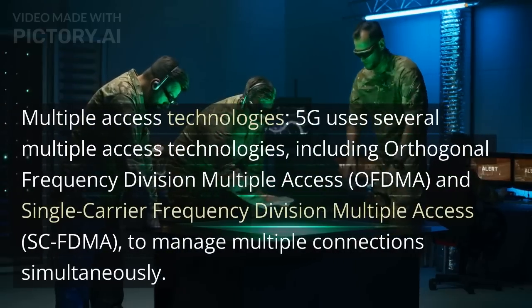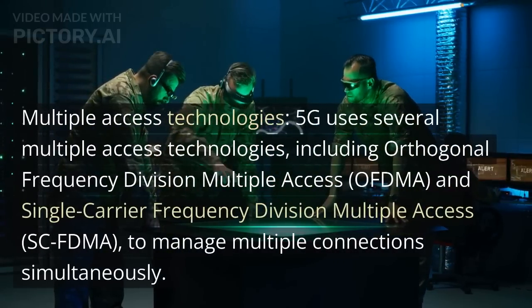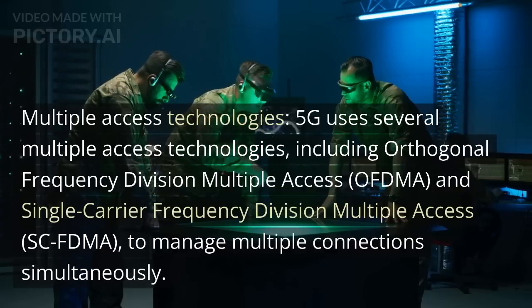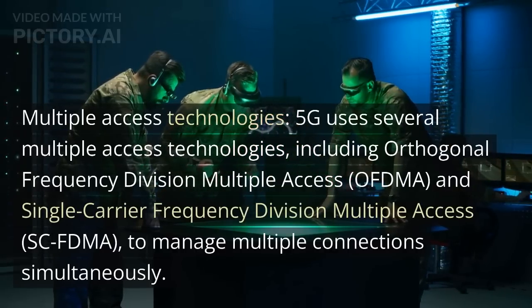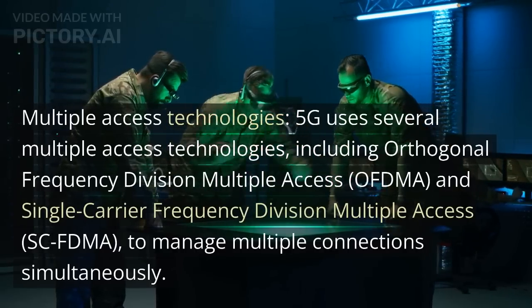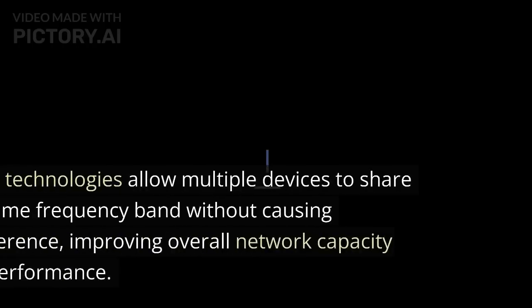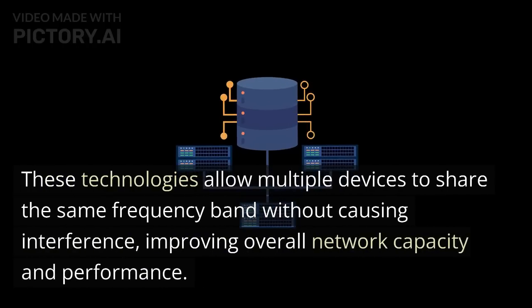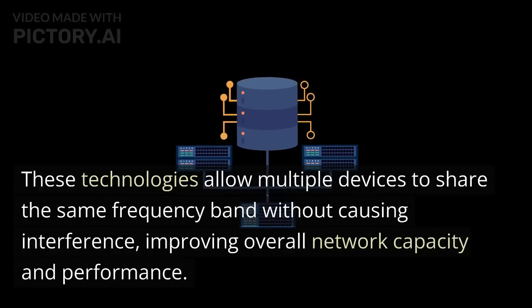Multiple access technologies. 5G uses several multiple access technologies, including orthogonal frequency division multiple access, OFDMA, and single carrier frequency division multiple access, SC-FDMA, to manage multiple connections simultaneously. These technologies allow multiple devices to share the same frequency band without causing interference, improving overall network capacity and performance.